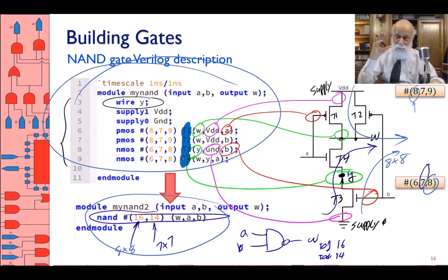I write it using the transistors, with their delays and all that. Then I perform simulations. Maybe I have for that structure 3 inputs, 4 inputs. I will change all of those. And then I will eventually find that, okay, for this particular change, my output becomes worst case in this situation, or my output becomes worst case for 1, worst case for 0.